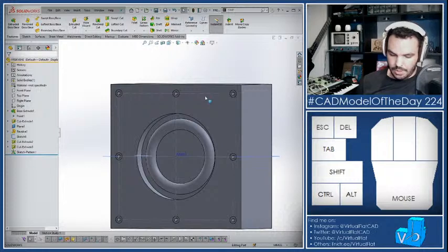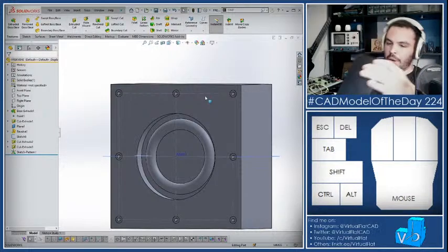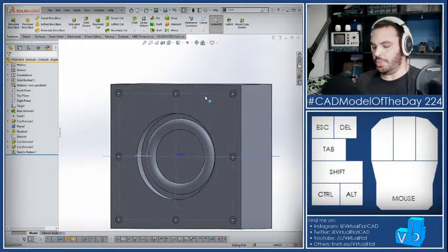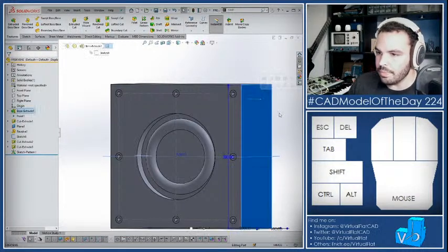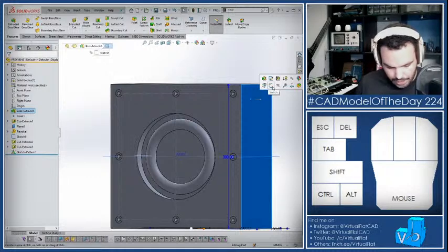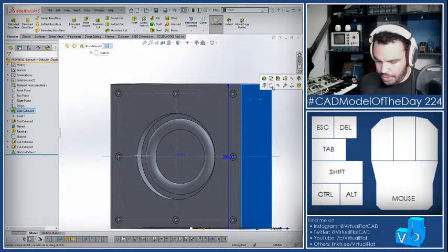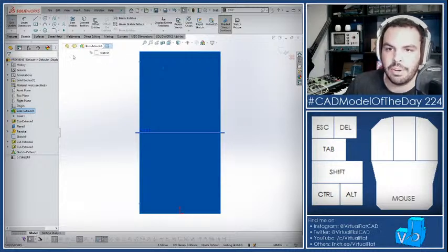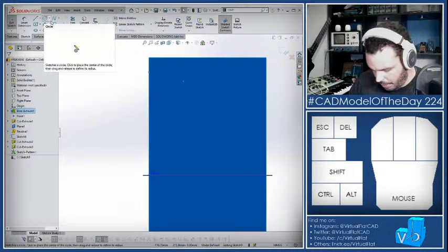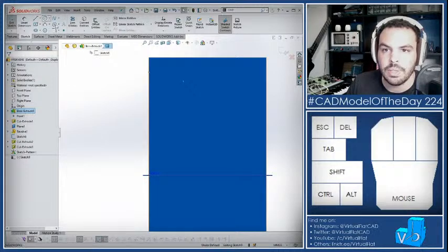So let's try it. The only thing awkward is that it's tough to know which is the bottom. I'm just going to start over here, and since this is a regular rectangular pattern, I'm just going to measure a feature and use my regular linear pattern. No need to overcomplicate, in my opinion.